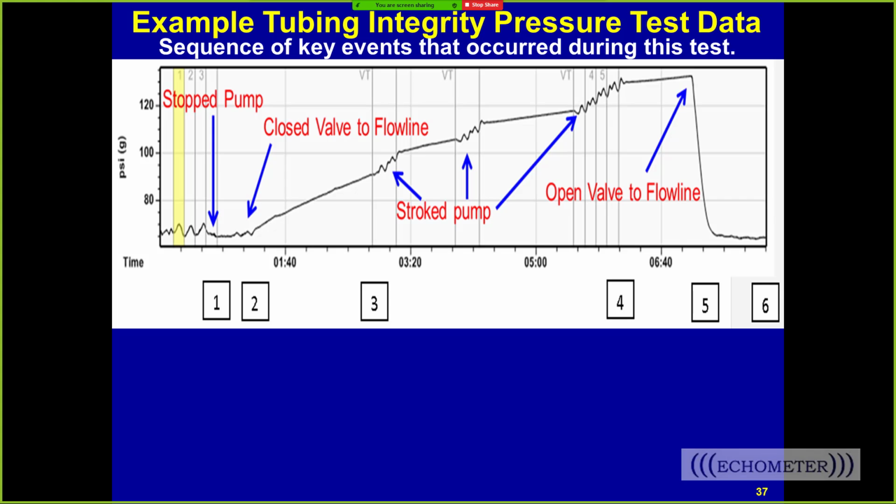So you need a stuffing box that you can pressure up and hold pressure on that's higher than the pump intake pressure, so the gas in solution won't come out and cause you problems while you're pumping the well.